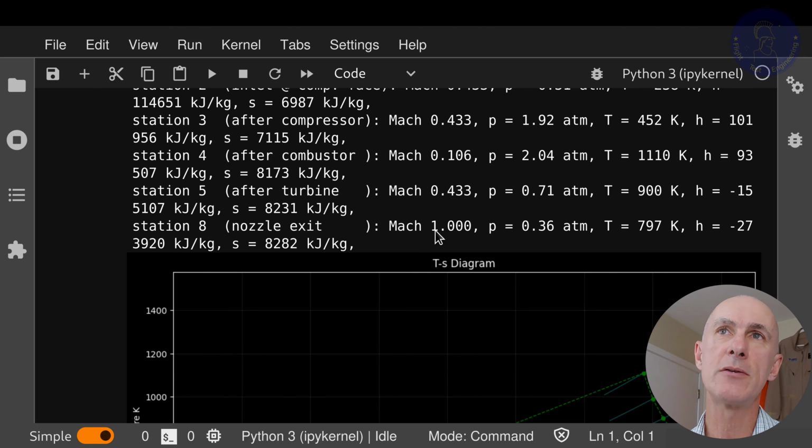One could ask, wouldn't it be worth it to have a convergent-divergent nozzle at the exit to better use this excess pressure and further accelerate the gas? Yes and no. From the ideal point of view, yes, the faster the gas, the more thrust we get. However, when we factor in the friction we would lose on the divergent portion of the nozzle, unless there's a lot of energy to further expand the gas, it turns out it's not worth it. This is why we do not see convergent-divergent nozzles in jet aircraft, only in rockets.